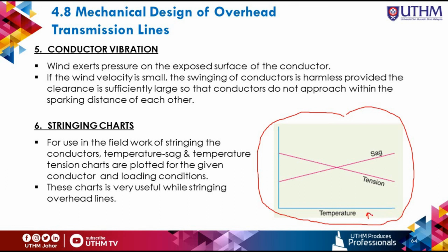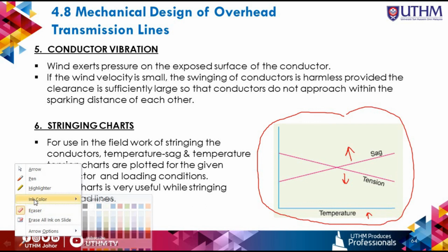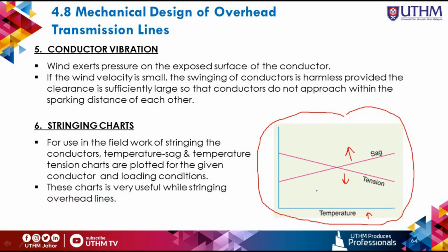When the temperature is increased, the tension will be decreased and hence the sag will be increased. However, on a cool day, the temperature will be decreased, the tension will increase and the sag will decrease.